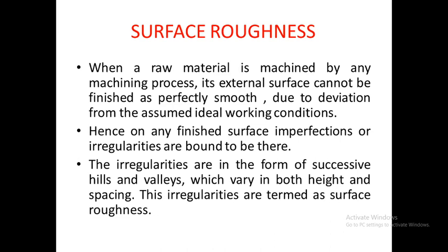So, if the surface is smooth, it leads to lower friction, lower wear and tear of the material, as well as less power consumption. Or we can say that the functioning of the machine is proper. However, if the roughness of the two sliding parts is higher, then it will result in higher friction between the two surfaces, which will ultimately lead to more wear and tear of the materials. That is, the materials will get eroded earlier, and there will be more power consumption.